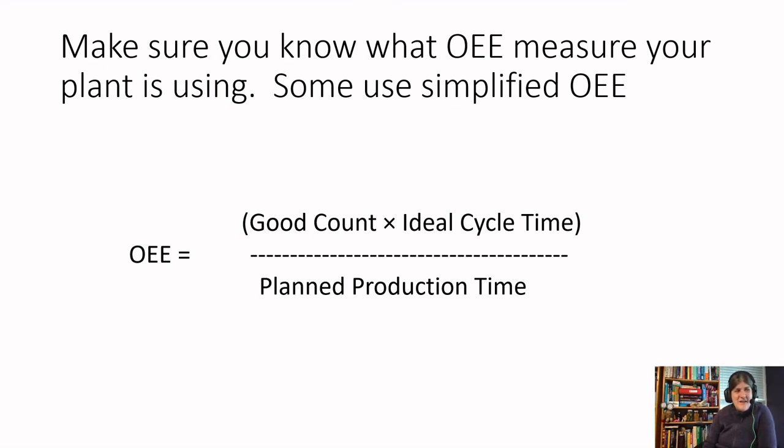Common cause versus special cause variation. One of the tools that we will be talking about shortly is called Shewhart charts, or what we may also be calling X-bar R charts. These are statistical process control charts, and we can see when our OEE scores are tracking and the variation we're seeing is normal, versus when that variation indicates we are losing control and need a much broader intervention from our part. This is part of that Six Sigma and process work that we've been talking about in some of our other videos.